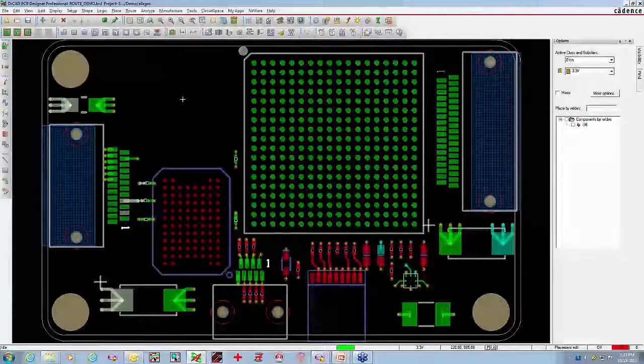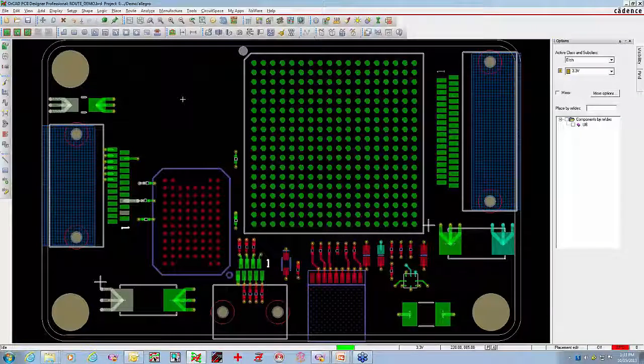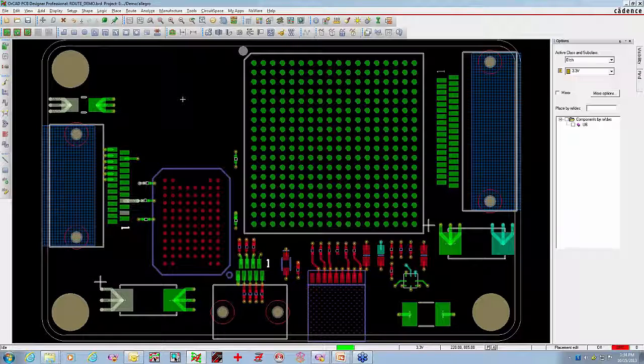So the next thing I want to do, and let's just tell you a little bit about the design itself. In this particular case, it's an 8-layer design. I'm going to be using an 18 mil via with an 8 mil drill. The default trace and spacing rules are 5 mil trace and space. And there's an area of the board that utilizes 4 mil trace and space, and that's that particular fine line BGA, the 0.65 millimeter. There's 3 BGAs total. There's 2 on the top side and 1 on the bottom side. And the pin pitches are a variety. I have a 1 millimeter pin pitch, a 0.8, and a 0.65 millimeter. So I'm just kind of showing you that you can have some fairly complex land patterns on the board, and we can effectively handle that in the Autorouter.